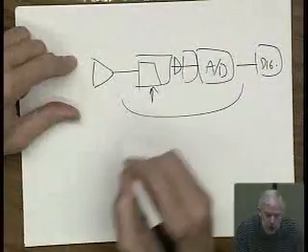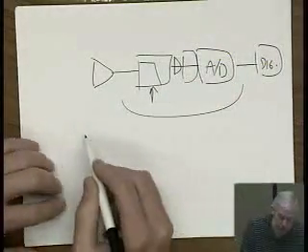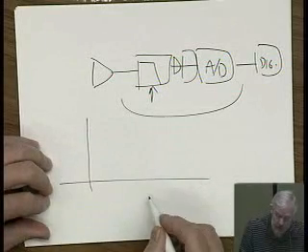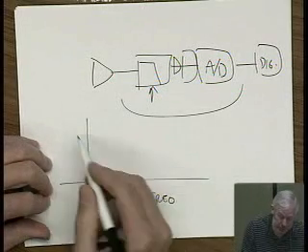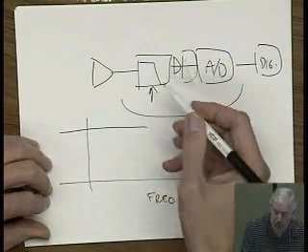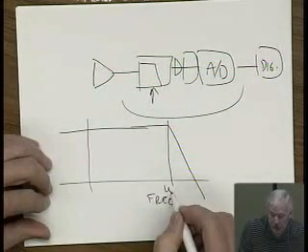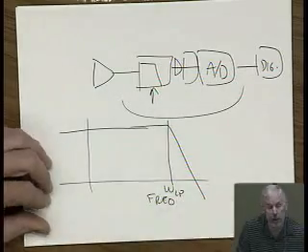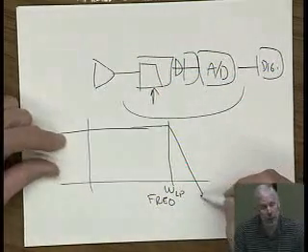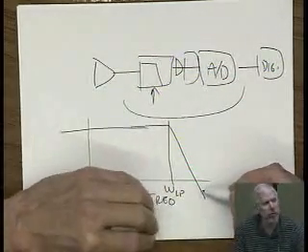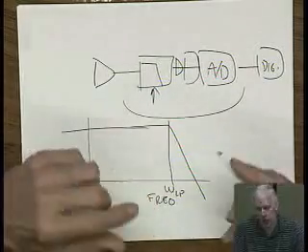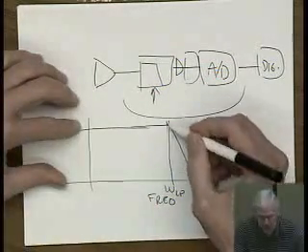So how do we do these filters? I'm showing this as a low-pass filter. What I mean is that as a function of frequency, if it's a low-pass filter, we want it to go out, and then at some cutoff, the low-pass filter cutoff, we want to design it so it drops off as fast as we can. So it's like our compensation problem in a way. But we want to make this really sharp.